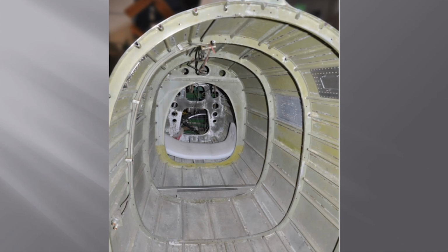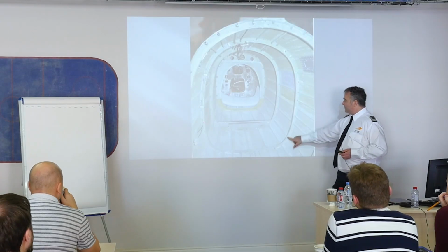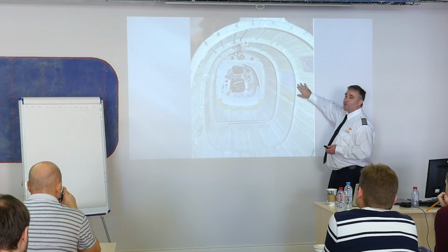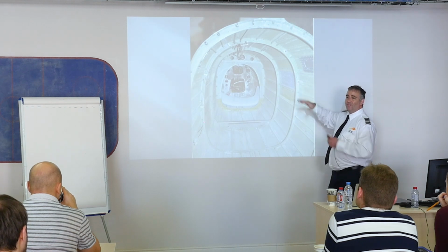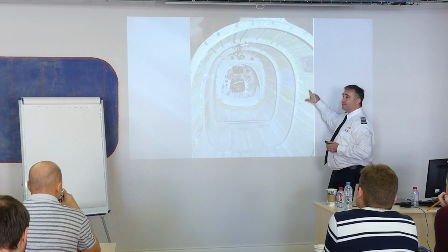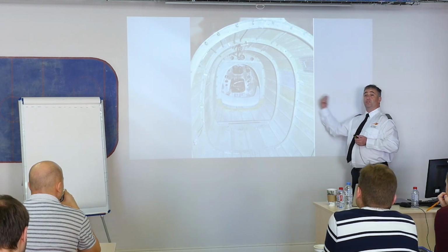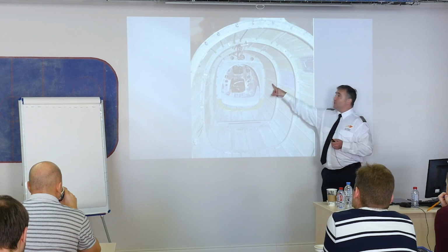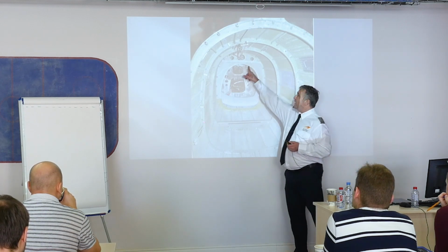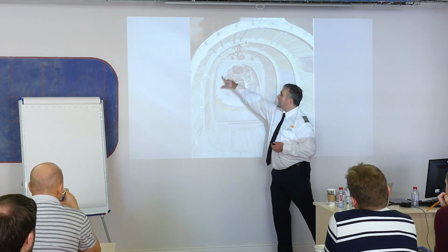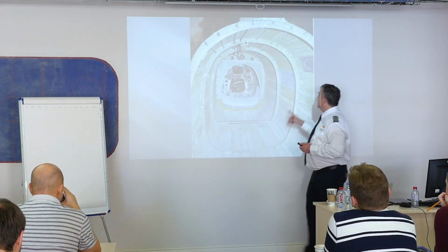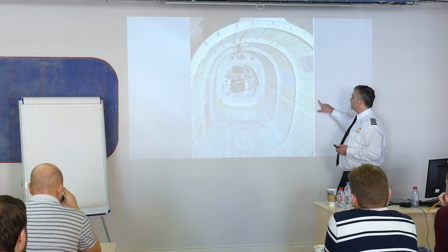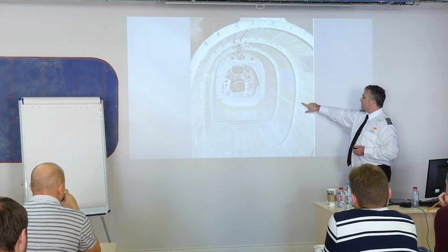This is an inside view of the fuselage. If you look, the fuselage also has these devices or this structural component. These are called formers. It forms the shape of the skin. The skin is on the outside, and that would be the part that we could touch, the part where the registration is written. November, whatever in the world is written on the outside of this. Attaching each one of these formers, and you can see here I have an actual bulkhead, or something that forms with rigidity, right? Attaching each one of these are longerons. That's what this one is called right here. And stringers.